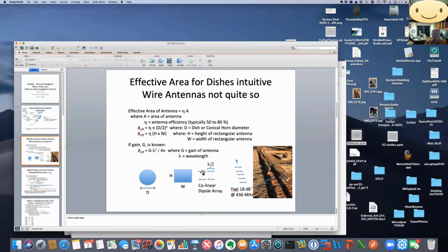So here's the dipole, and in this example, I made a collinear array instead of a dipole, and a dipole beside it, and a dipole down here, and a dipole down here. It turns out that the effective area of the dipole includes the area subtended by this entire array, including the vacant area in the middle where there is no dipole, because the resonant dipole has a certain capture area that's something like half a wavelength or so all around the dipole.